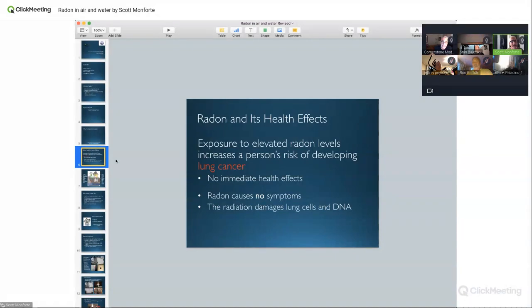It may not. And again, when we test as inspectors or radon mitigators, you can't close the house up on an elderly lady that doesn't have air conditioning, especially this time of year. You've got to do the best you can. But yes, you're correct. If the windows are open on the second floor, you could actually increase the radon levels by creating that stack effect, air going up and out. Basement windows, if you open them, you're probably not going to have an issue. It's going to dilute it. Just on the second or third floor of the home, you could elevate those radon levels.